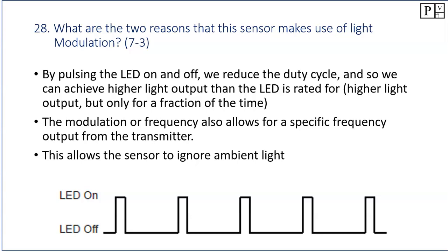So the beauty of using light modulation is that you can turn the LED on and off, and you're looking for a specific frequency back. It's not going to change state until it sees that frequency.